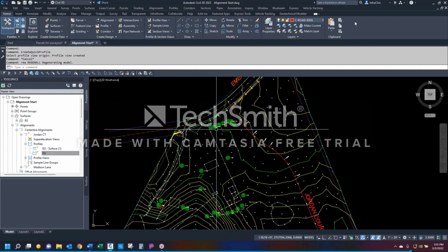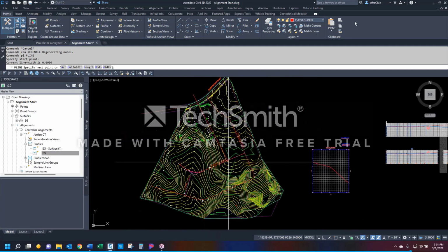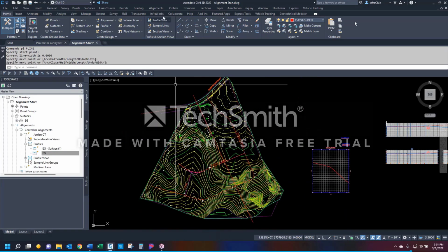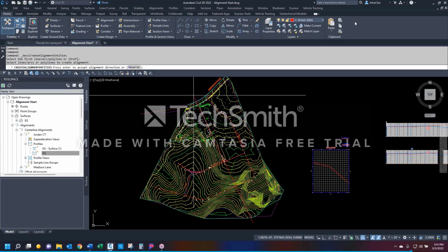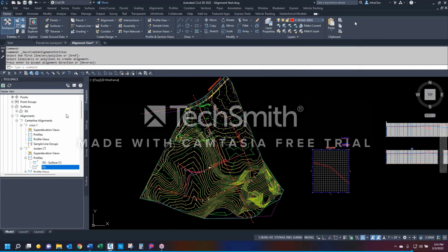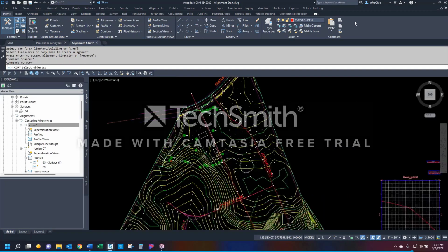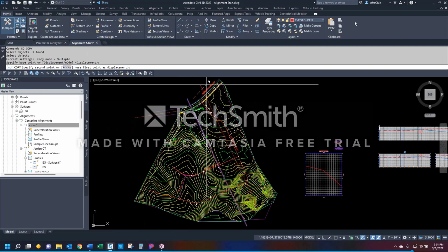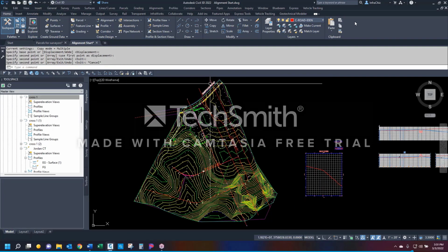So like I could do this. Let's say that's the cross-section I want. Alignment, create it from a polyline, select it, looks good, sounds right, cross 1, right? Turn that off, erase it, sure, looks good. Okay, it's there, and here it is, cross 1. So now if I copy, CO, grab it, and they say, I want 2 more, right here and right there. Cross 1, 1, cross 1, 1, 2.